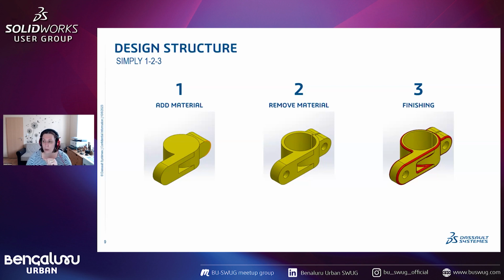The reason number 2 is if you decide to 3D print this part and export as STL, a fillet has tons of triangles inside, and at the same time it's really hard to print. So for a 3D printed part, you would like to suppress the fillets and then save the STL and print it. And if the fillets are not at the end, you won't be able to do that, because you probably already placed relations to that fillet, and when you suppress it, you suppress also features.